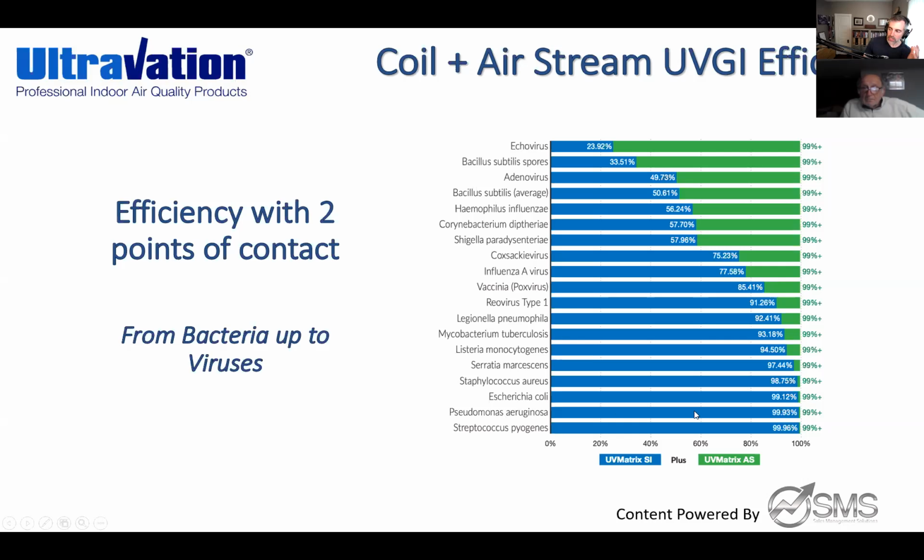But if you're truly trying to get maximum disinfection and maximum efficiency with your UVGI technologies that you're putting in here, then you really also need to apply an airstream application as well, especially if you are trying to address these more airborne viruses and spore components. So great, I could start at the coil, but if I care about airborne viruses, I really need to be looking at an airstream application as well.